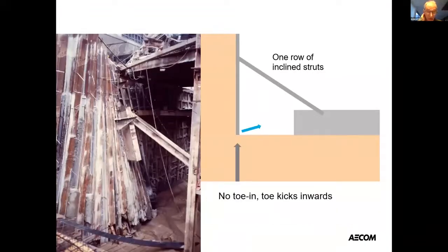And the reason for this failure was really very simple. You can see here that there's steel sheet piling, which was not toed in because there was rock exposed at excavation level. And when the lower strut was removed, there was a mechanism. I think this is elementary structural analysis, but nevertheless, people on site remove struts and leave one strut behind when two are necessary.